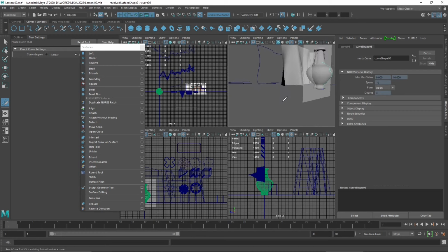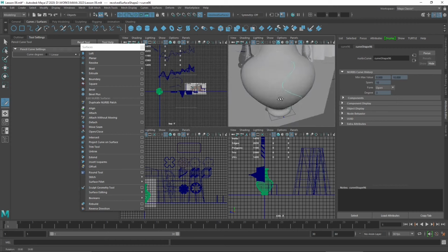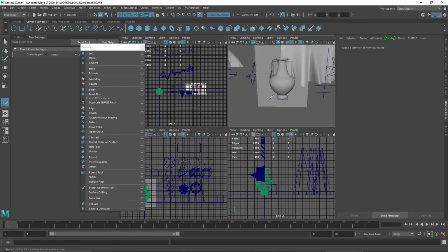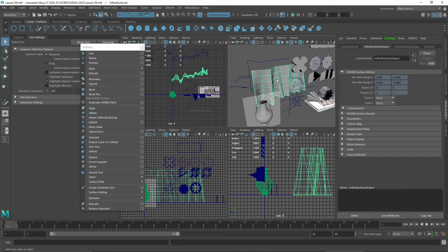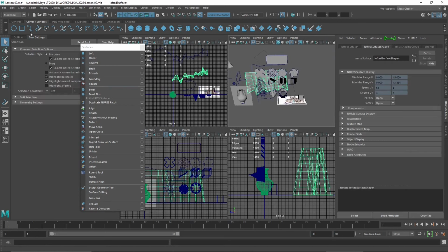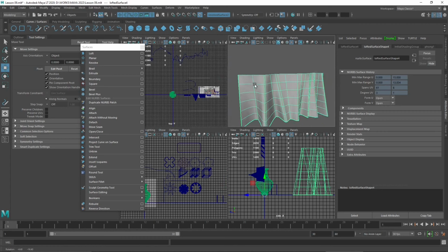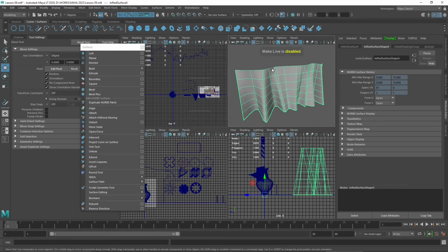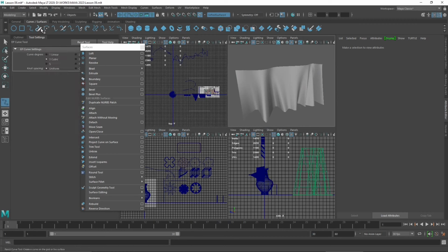Now the first thing here, if we turn on the live snap that we saw also earlier, we use that with work planes. If we turn that on, you can directly draw curves on objects. So you can use 3D objects to create more curves based on those surfaces. So all you need to do when you activate the live surface is to select a surface. You can see there on the top that is telling me that I have selected that. Now that's no live surfaces, and that's lofted surfaces. So that's the one that we created earlier.